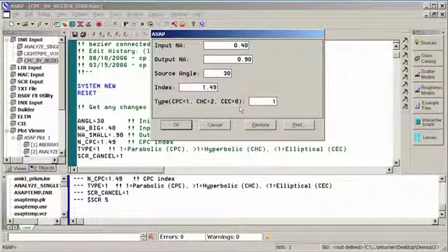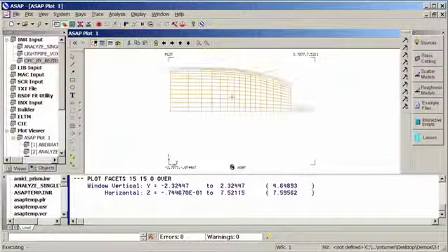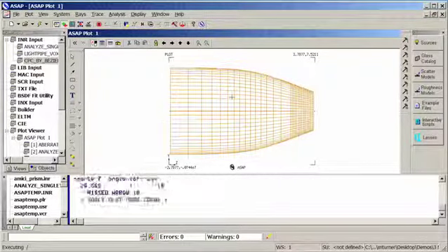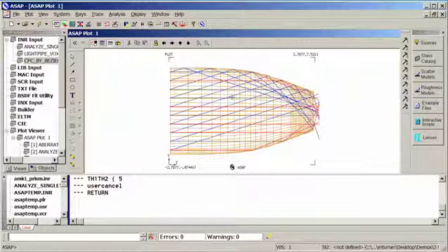What I'm going to do is let ASAP design for me a simple compound hyperbolic concentrator. So I'm just going to change this data entry and then click on OK. Now ASAP has defined the geometry for my concentrator, and we can launch rays through the system. We can vary the angle of input, and we can do analysis at the output plane to determine what the efficiency is and any other information we might need about this particular concentrator, or we can use this concentrator as the input or output to any other optical system.